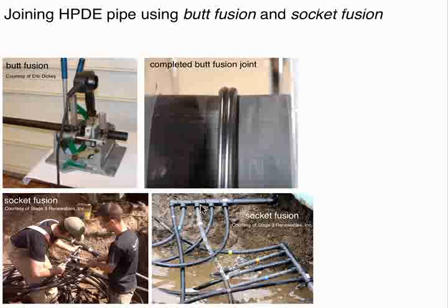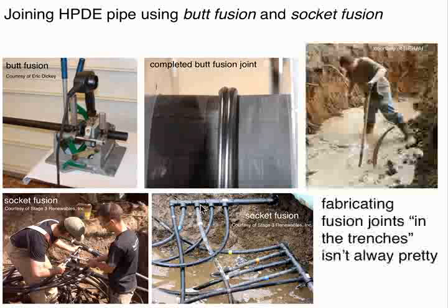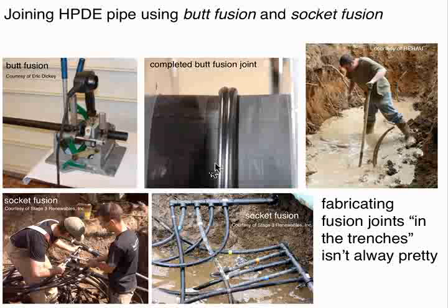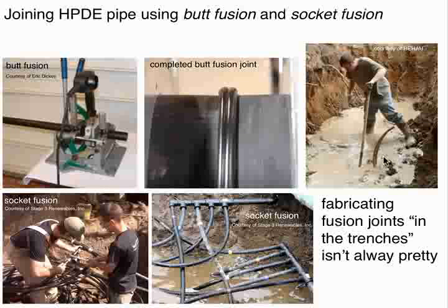But I want to convince you that it's not always a pretty picture in an earth loop trench. I'm sure some of you have been in trenches as I have. I've actually had a trench partially collapse on me. Learned a good lesson. Fortunately, from the hips down, I was able to get out of it, but this is a mess, and you can imagine trying to get in here, clean these pipes up, and do this fusion.